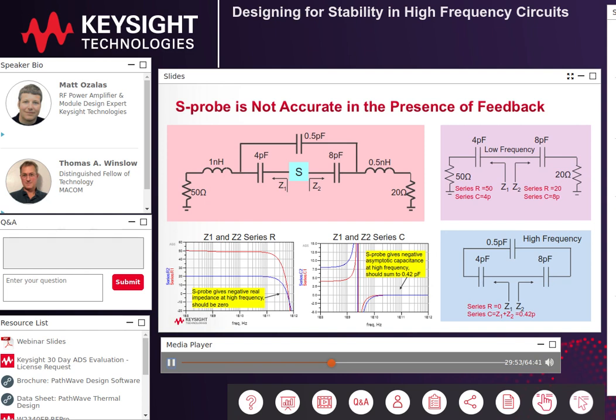This new probe approach has been fundamentally reformulated and provides absolutely accurate bidirectional impedances, bilateral and unilateral loop gains, open port impedance, series loop impedance, and the driving point impedance of a given node under arbitrary levels of feedback. This new probe can also be used in ad hoc pairs to analyze arbitrarily defined subnetworks within your overall circuit. Think chain analysis, where you define probe pairs, and the probes acting together as a pair can completely analyze any subnetwork block between and outside of the given probe pair. This full analysis capability has never really been so easily available before